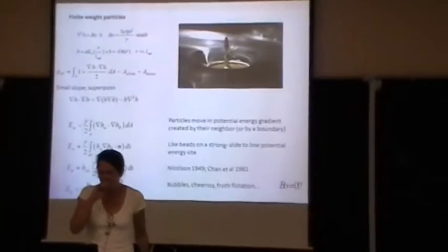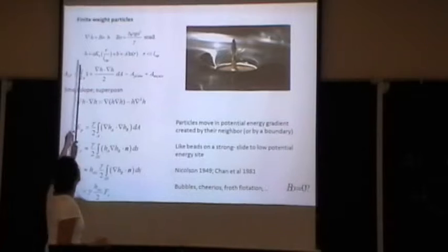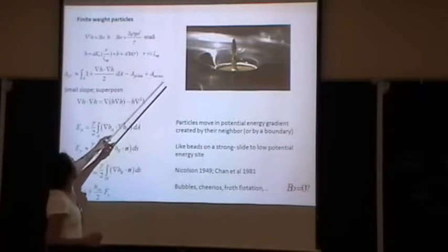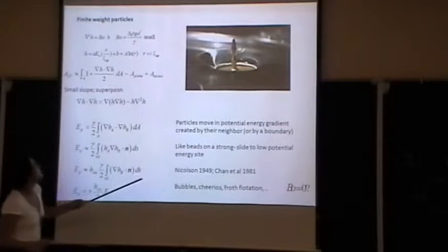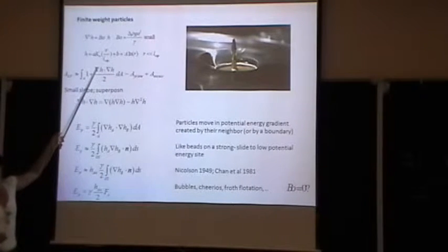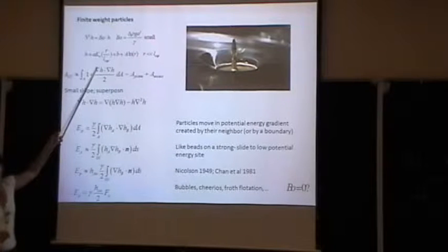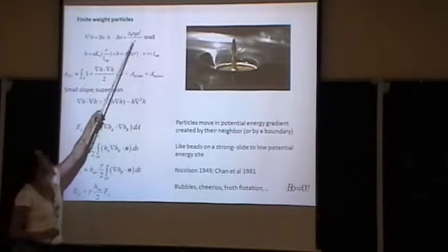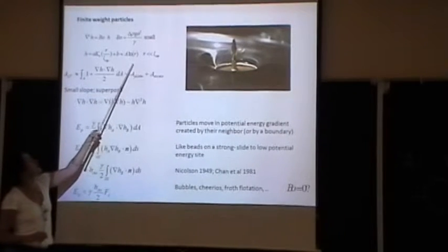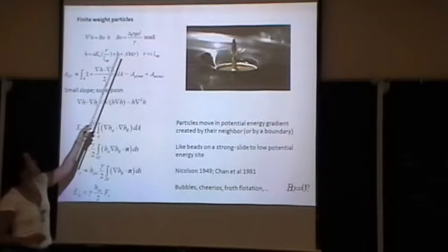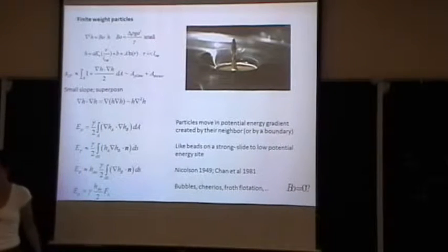Okay. So he said the Young-Laplace equation governs the shape of the interface. And here A is what I call the particle length scale, and he assumed that was small. If we solve this, we're going to get a Bessel function in cylindrical coordinates. And near the particle, for lengths small compared to the capillary length, we can approximate that as a logarithm. We're also going to be able to approximate this as just a Laplacian equal to 0.